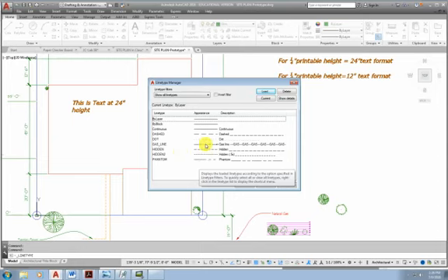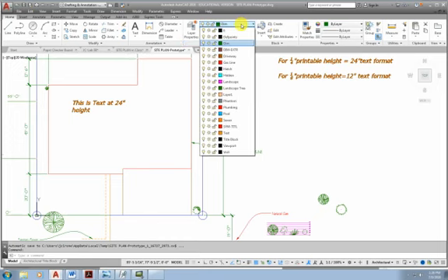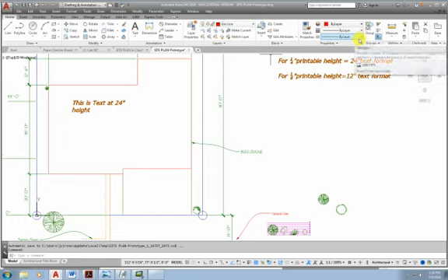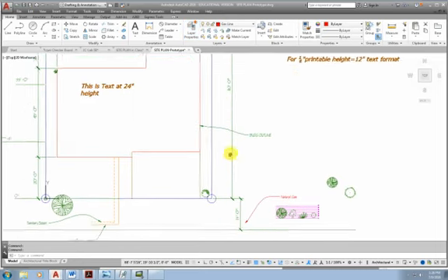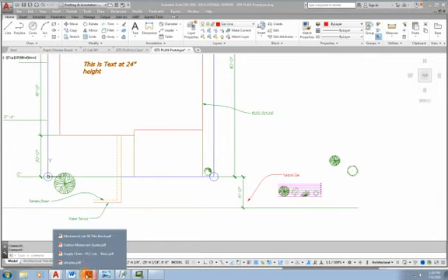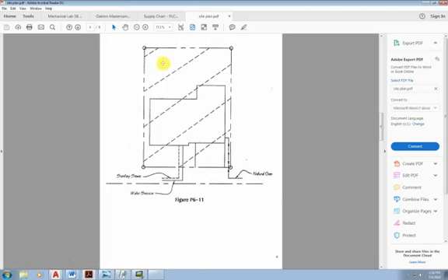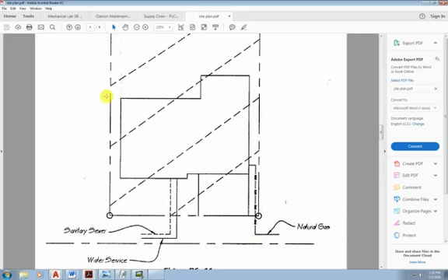So what I'm going to do is enable it. Let me just close out of that. Then I'm just going to say okay, let's see what layer that would be. I'll put it on the gas line layer. Now it should be by layer, so let's look at the properties of it. Here's the gas line layer. The line type properties will match. It should be fine. Once that layer is current, all we need to do is create the gas line, and it's just regular straight lines. You could spline it, but we're just going to do straight lines with that.